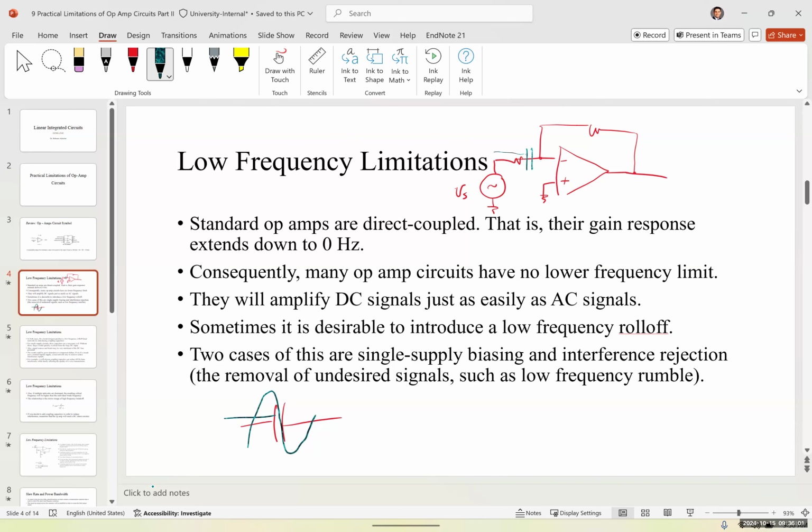type of circuit that requires a lower cutoff frequency is a high pass filter. So anything that has a high pass filter, where we want to block the lower frequencies, also has a coupling capacitor. One example of these high pass filters is when we have noise at the lower frequency, which we call the humming noise or sometimes the white noise. And I gave you an example of electrocardiogram, ECG or EKG as they call it in Europe, which are used to measure heart rates.